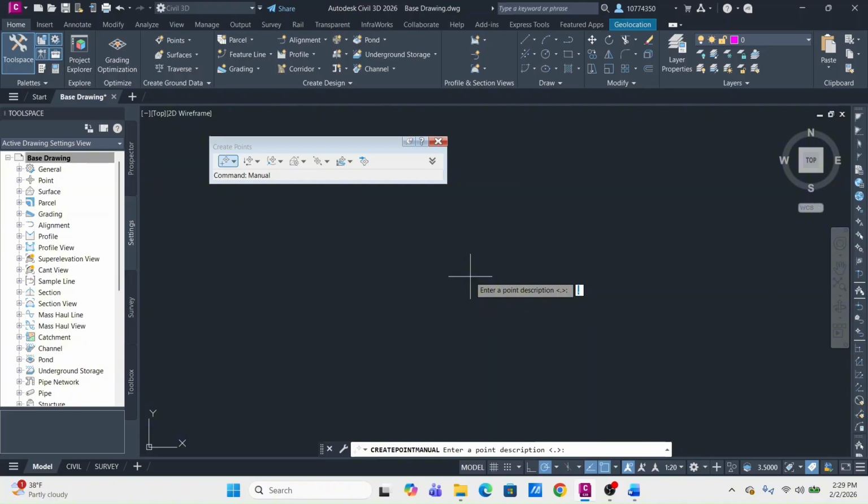Since this is a calculated corner, we're just going to call it, it's a section corner, so we're going to call it, whoops, make sure your caps is on, SECTION CORNER CALC. You just hit enter. Specify point elevation. I don't care about that right now. We're just going to click 0. I can always enter that in later. And then boom. Here's our calculated section corner monument.